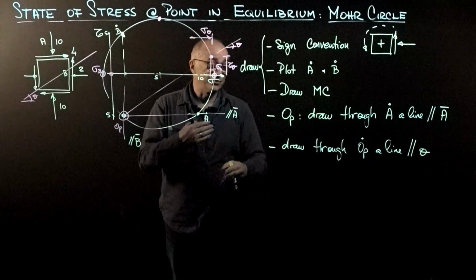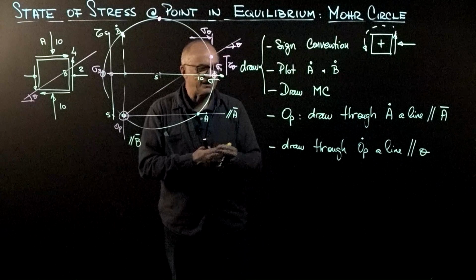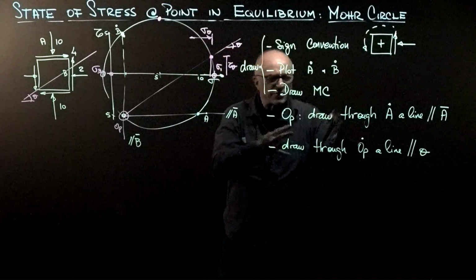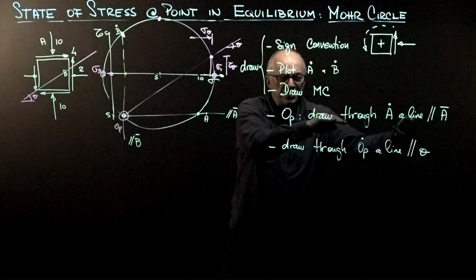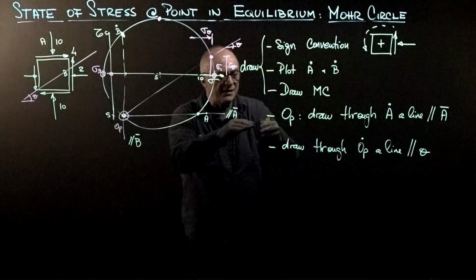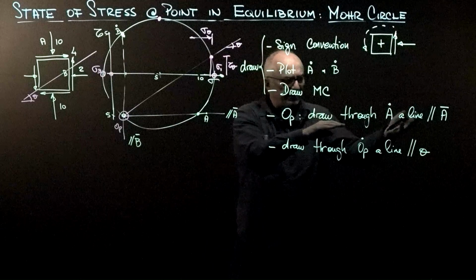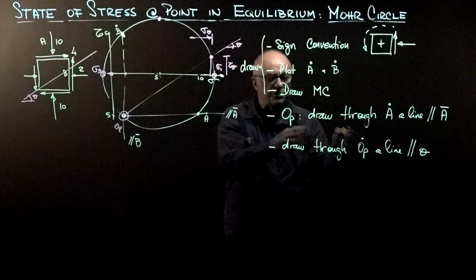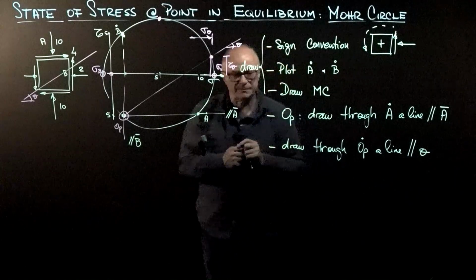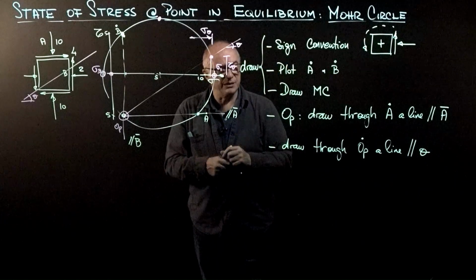Now I can use the converse relationship. By the way, notice that there is a little bit of Maxwell reciprocity in this procedure. The same methodology I used to define the origin of planes from a known state of stress and directions, now I can use to determine the state of stress in any direction from the origin of planes. Let's see one more implication.